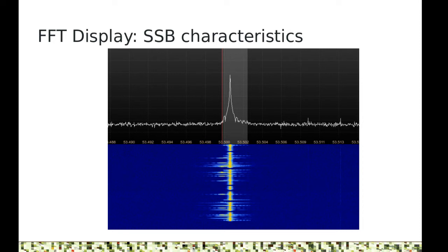For just plain old voice, that takes up to 3 kilohertz. Anywhere between 0 and 3 kilohertz, it fluctuates in that range. And if you have an AM signal, it takes plus 3 kilohertz and minus 3 kilohertz. So now you end up with a 6 kilohertz wide bandwidth, and everyone agreed that that would be very inefficient to transmit when you only need half that.